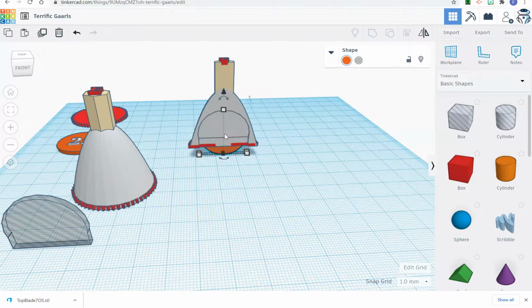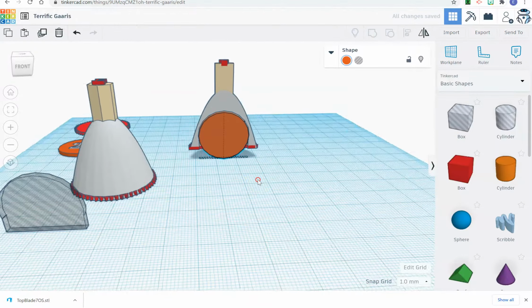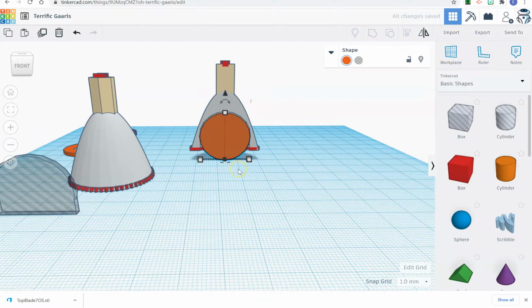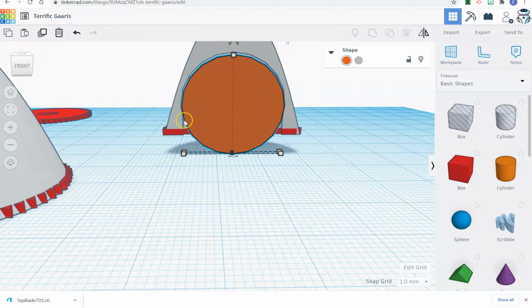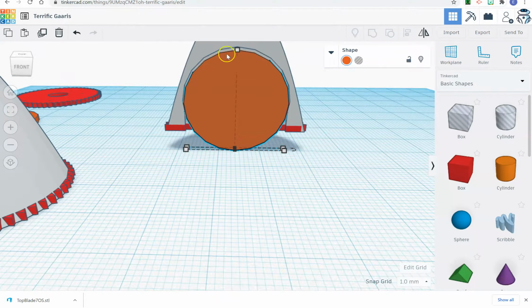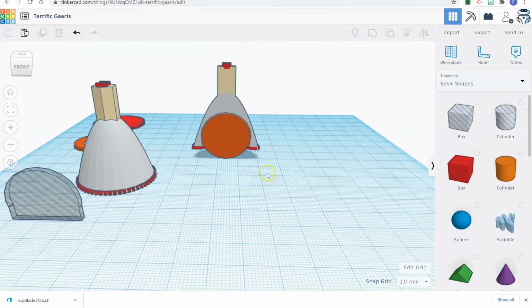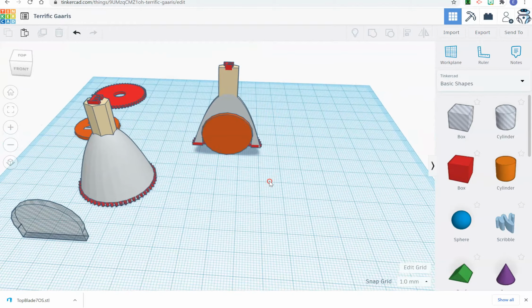And look at that, it should fit quite nice right in there. And you can see that it is this design here. So this, making this wider opening allows the quarter to go in, but it's these little edges right here that we've designed, which will actually keep our quarter nice and snug in there. We've got a little bit extra tolerance up here, which is good. So that's how you go and design your top for a quarter. And as I mentioned, it'll fit an American or Canadian quarter.